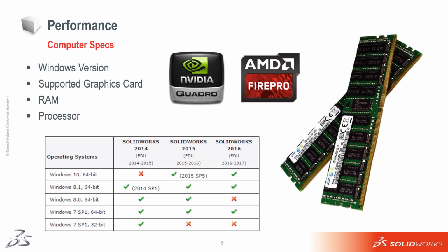But if you are working with a lot of large assemblies, that is a RAM intensive task. If you're doing a lot of multitasking, that is a RAM intensive task, and you probably will notice a difference going from 16 gigs to 32 gigs if either of those describes the kind of work that you do. Now for the processor, we typically think that the processor is 100% the most important thing. SOLIDWORKS usually is more RAM intensive.